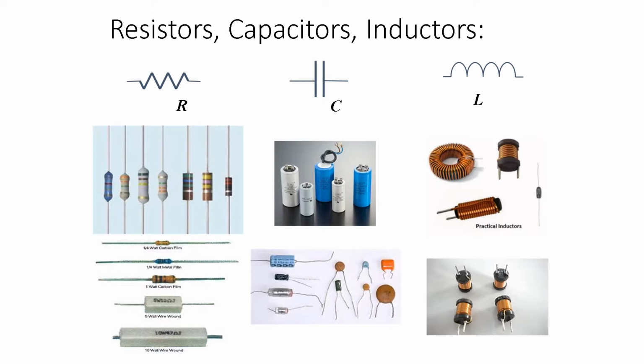But I just want to get you to know that there's a whole bunch of different types of resistors based on what material they're made from, based upon their manufacturing process. In the bottom left, we see different wattages allowed for resistors. So let's just say a resistor is rated for 1/4 watt carbon resistor. A lot of ours are like 1/4 watt carbon, 1/4 watt metal. Usually in the lab, you'll see mostly a fourth a watt. So that's kind of like their power rating.